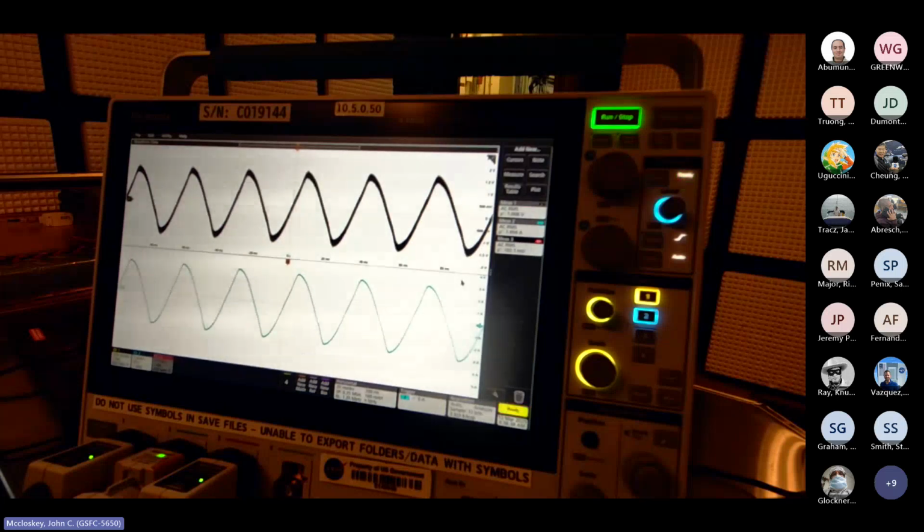So minus 9.7 dBm at 30 hertz to give... I'm going to go ahead and write down all the significant figures. 4 significant figures is overkill, but I'll write them down anyway. The first decimal place is probably all we need. But okay, the 1.008 volts AC RMS.